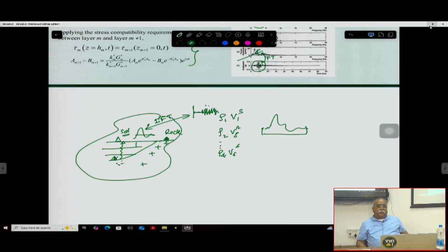If you put that site response component in the stochastic simulation as a 1, then the time history you generate is for the rock, and you put it at the bottom of the site. Then you use the SHAKE program by defining all the layers from your geotechnical data.